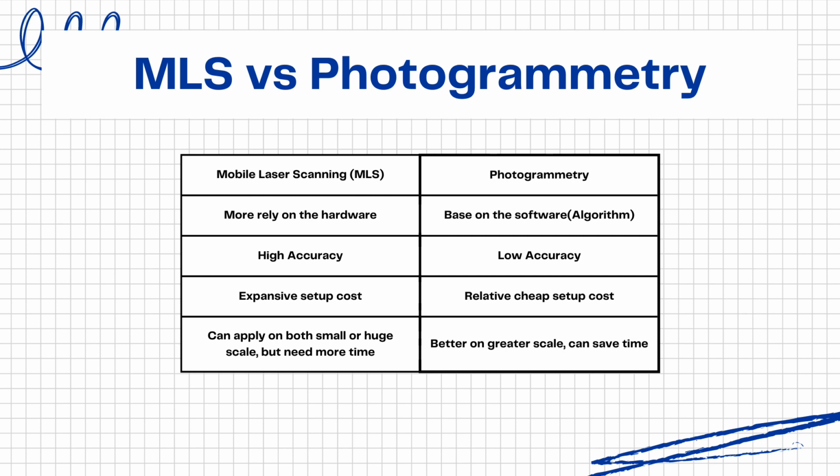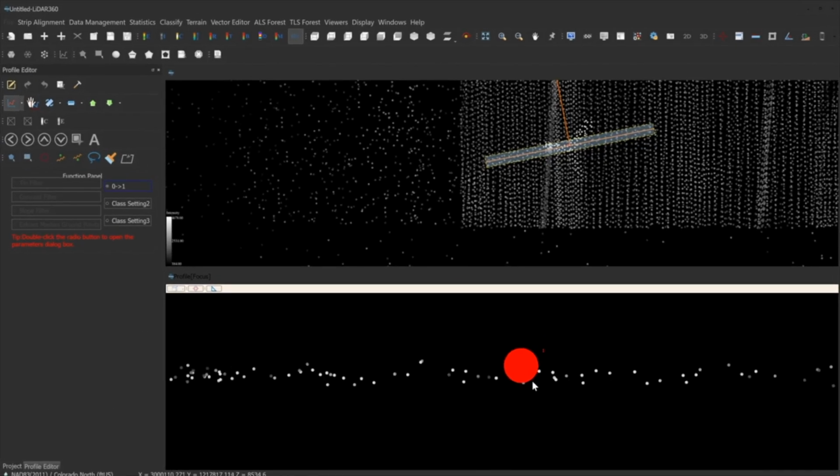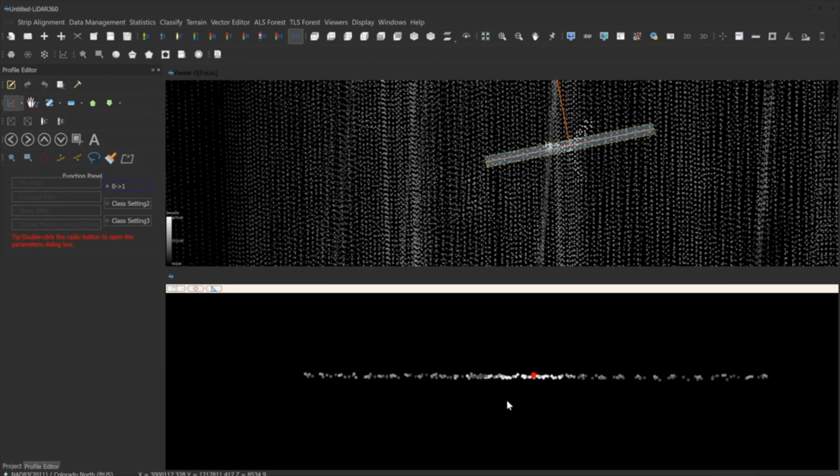Modeling is a big technical field. Although the results of 3D models are created by detecting the distance between the device and a single point on the surface of an object, the techniques behind them are very different. By combining the data with other sensors such as GPS, accelerometer, and camera, it computes 3D models using the coordinate data and colors them with images taken. Two common ones are mobile laser scanning and photogrammetry.